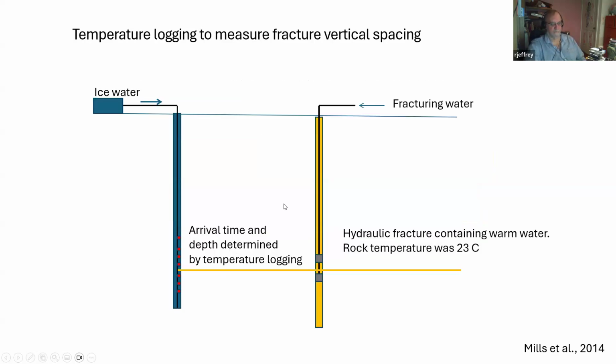So in order to verify we were getting good preconditioning, a primary concern was, could we put hydraulic fractures in at 1.25 meter spacing and extend them to approximately 30 meters as parallel fractures without them diverging or converging.